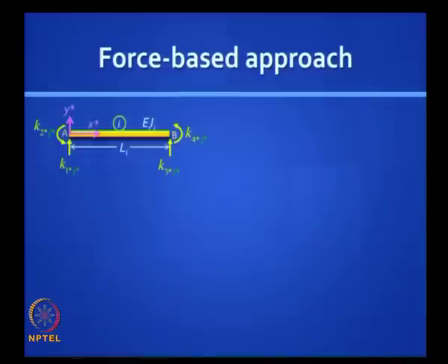And lastly, you have a force based approach where you write down an expression for bending moment at any section considering a free body. Can we do this? Take a free body, and in terms of your stiffness coefficient, can we write an expression for bending moment? Right? See, your support reaction is K1 star J star, and your end moment here is K2 star J star. If I cut a section here, the sagging moment expression, will it not take this form?